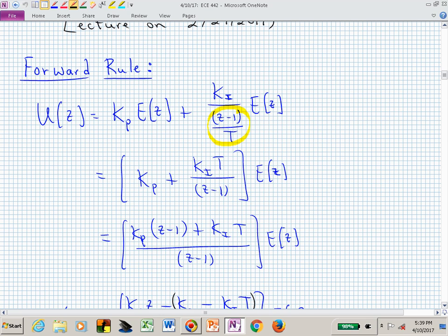If we can stabilize the closed loop system, once we have an integral piece in our controller, we now can integrate the error away when we have constant inputs. Meaning, I put in a 4, I'll lock into that 4 with my output if my closed loop system is stable and I have a PI controller. I'm forcing that behavior by putting that integral into my controller. That's why we may want to move beyond just a proportional controller. We may want to move up into a PI controller, or proportional integral. And it's for that reason. We are trying to enhance our steady state accuracy specifications or our steady state error behavior.